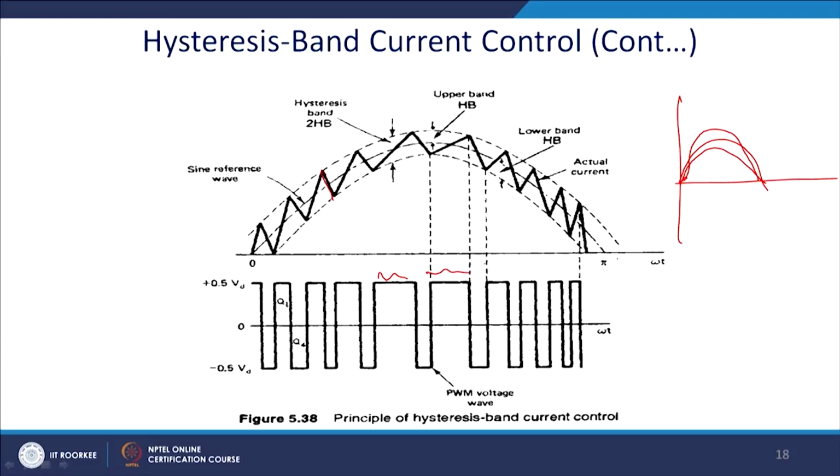You can see that the widths are quite big in duration in the middle to reciprocate the area of the sine curve, and it is almost the same as the sine triangle PWM. But the problem lies in that the frequency of this current is not constant, it is variable. So, designing a filter for it is a little painstaking.